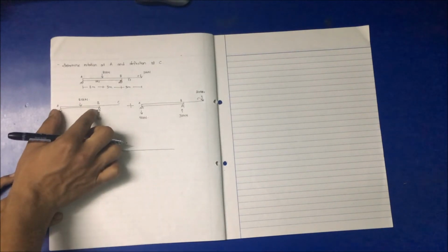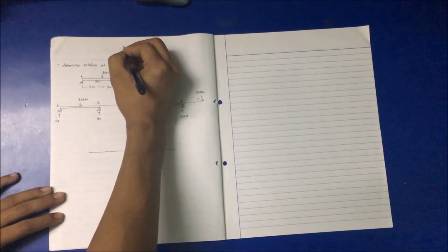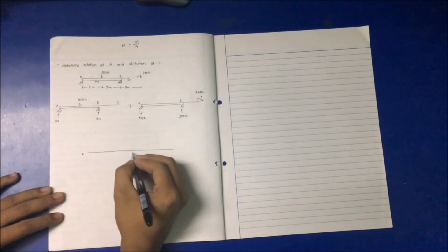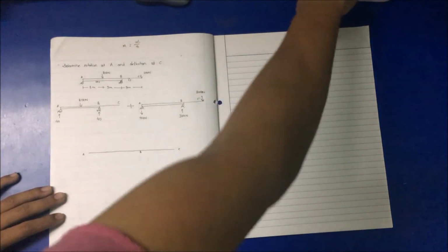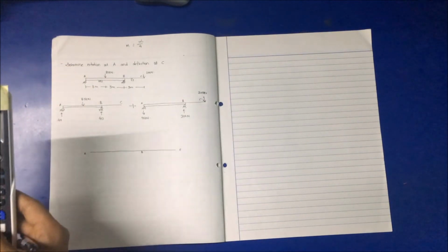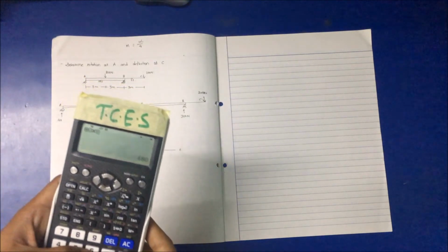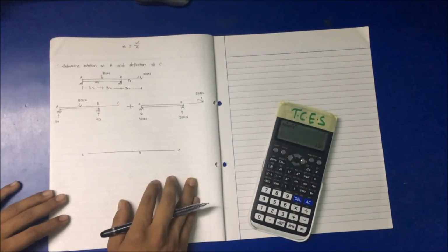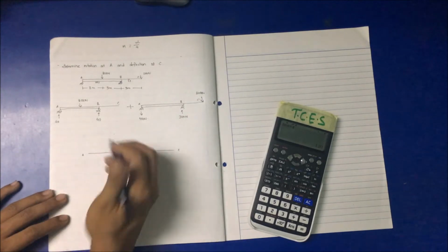80 kilonewton, and for this case the formula for bending moment is WL by 4, okay, for a point load at the mid span. So if I write this A, B and C, 80 kilonewton, 80 multiplied by length 6 meter divided by 4, this is 120, okay, 120 by EI.